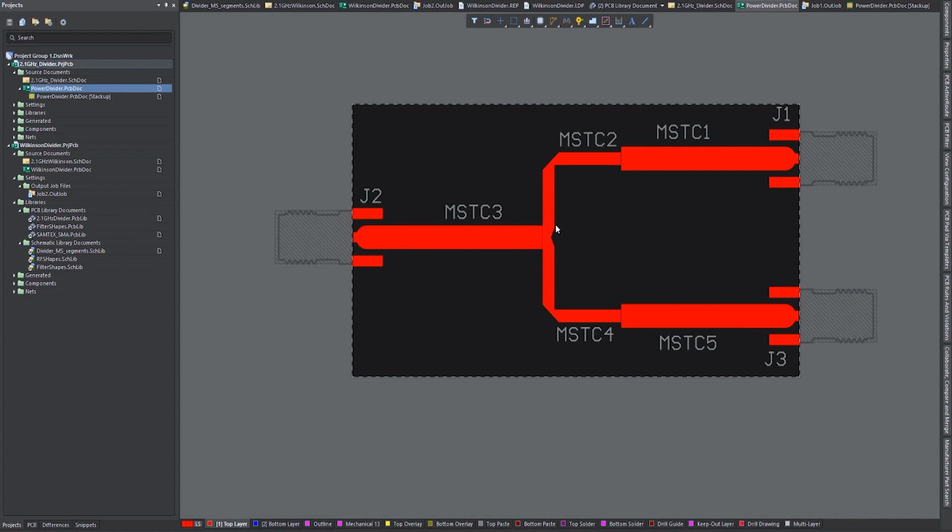But you can see I've got that notch in the t-junction. I've got my ideal right angle corners on my quarter wave transmission line segments, which are actually components made in the copper. And then that's what I milled, and I measured it, and it works great.